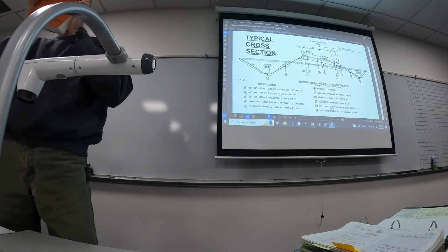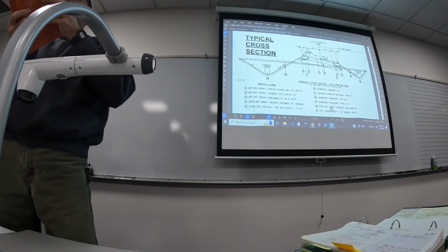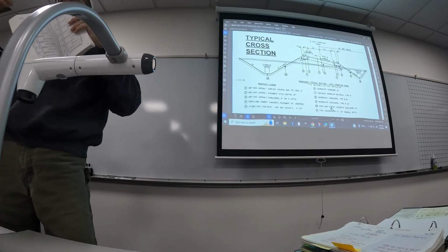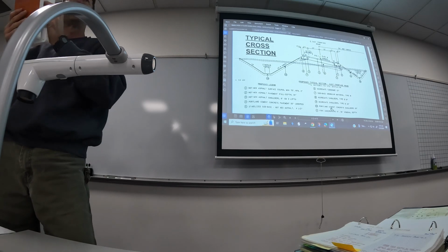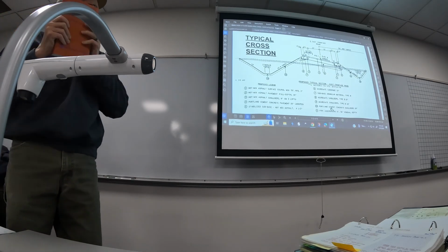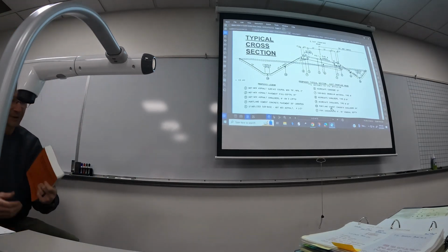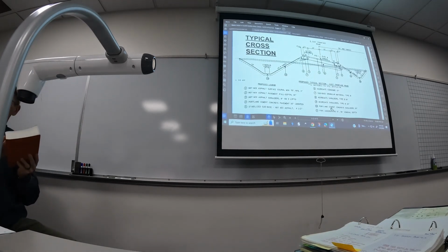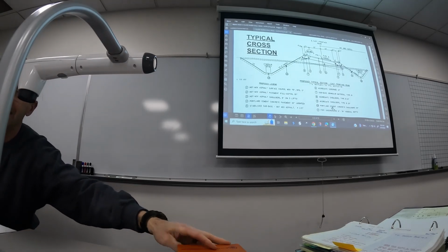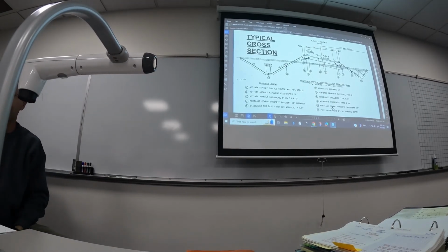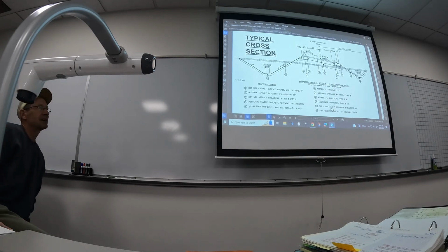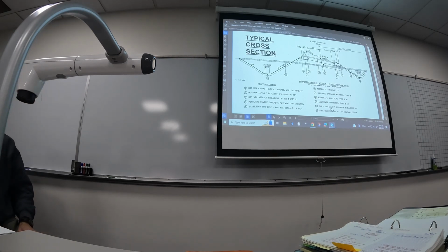How about this? This looks like a Bible. This is the Bible for roadway work, the IDOT spec. It follows the same kind of components where everything has a section to it, but the numbers aren't like 1, 2, 3, 15, 16, all the divisions. It follows the same premise, so if we needed to look at concrete pavement, section 400 covers everything concrete-wise. So it's set up the same way, at least the specs are. If you have a development job, usually those are like the master spec. Is that the term you know, master spec or CSI master spec? It follows that. That's how the divisions work.